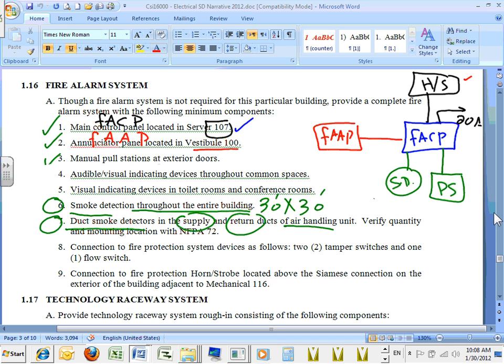But all you need to do now, everybody knows what an air handling unit does. It takes the air and circulates the air in the building. So if you want to heat the building, you bring hot water into the air handling unit. It throws air through it, it becomes hot air and it circulates through the building. Heats it, brings it back, heats it again, brings it back.